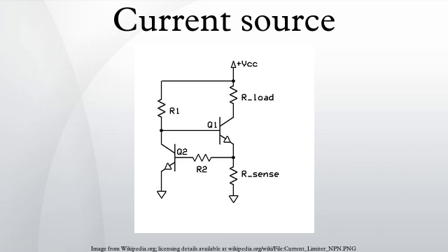Conversely, a current source provides a constant current, as long as the load connected to the source terminals has sufficiently low impedance. An ideal current source would provide no energy to a short circuit and approach infinite energy and voltage as the load resistance approaches infinity. An ideal current source has an infinite output impedance in parallel with the source.